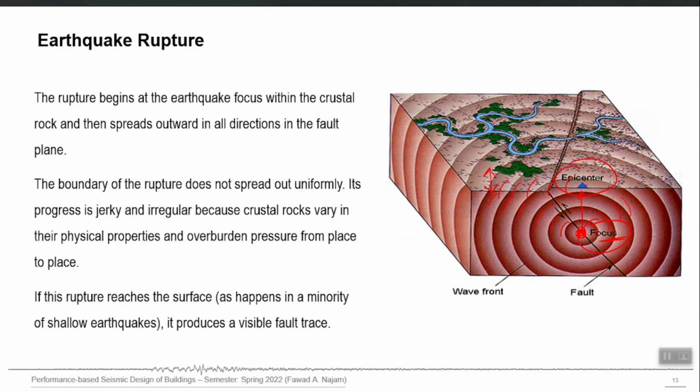That difference of 20 seconds, 10 seconds, 5 seconds is directly convertible into how many kilometers you are away from the epicenter, right. So if you have that difference at 3 different locations for the same earthquake, then you can identify from where exactly that earthquake was generated. That's how we identify the epicenter, right. Within maybe a few minutes of an earthquake, you have seen in the media and news that they can tell the epicenter, right.